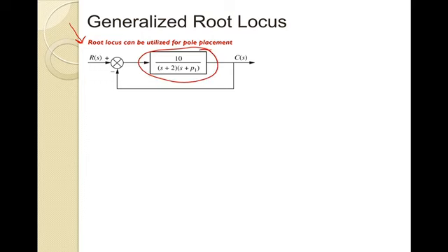We've already defined one pole, in this case -2, but the second pole we haven't defined, and so here it's at P1. So maybe as we're designing a system, some hardware, an electrical system, mechanical system, etc., we might want to design our plant, if you will, and we might say, hey, where could we place a pole to get sort of the open loop characteristic to be where we want, and then later when we put in some gain, we could basically shape it in a direction that we want as well.